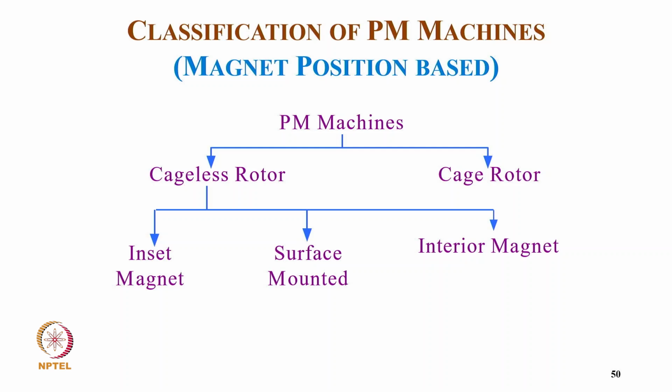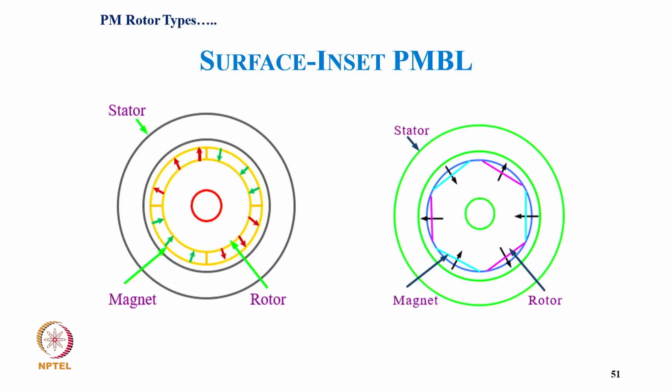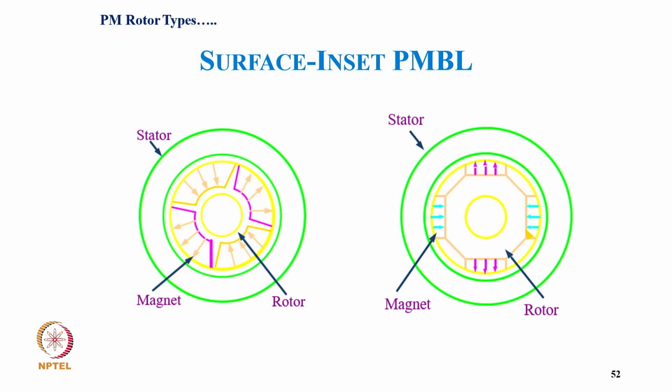Sometimes even interior magnet also, because to operate the motor at high speed, typically sometimes 3000 to 6000 RPM, as you have seen in case of two-wheelers and three-wheelers. And these are, of course, surface and inset types of magnets, how we really put the magnets in magnetized form, and magnets typically on the surface in different geometries. There are typically more than 30-40 geometries for this kind of motor.